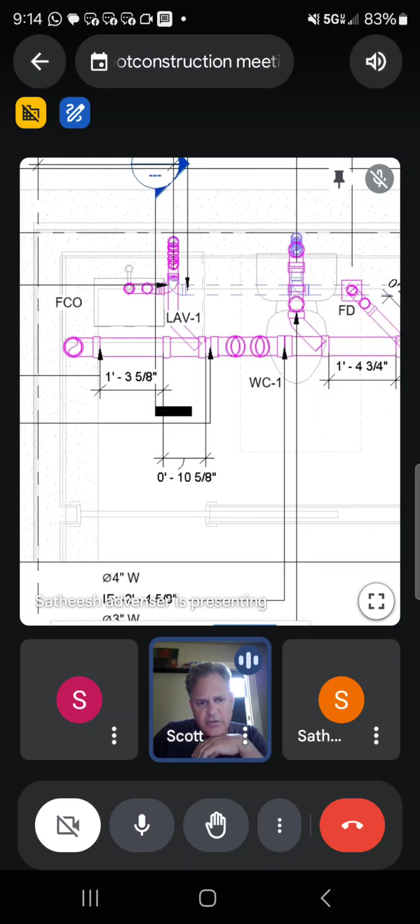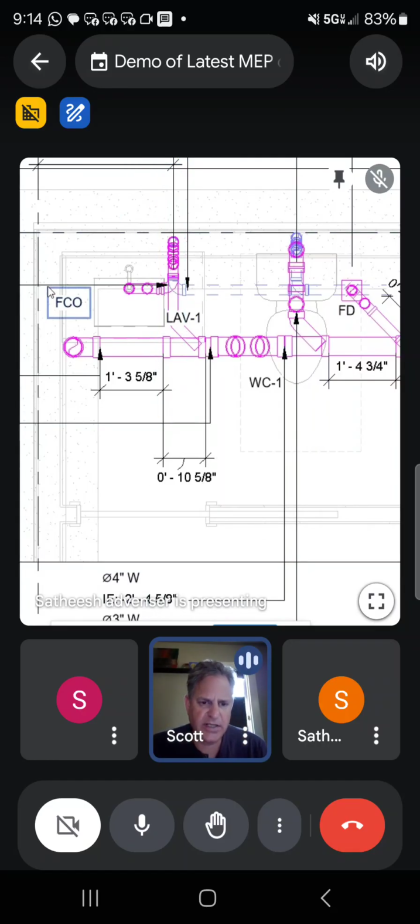Any penetrations that are coming through the floor, maybe pick a grid bubble. I see a grid bubble there. Maybe a grid line, and pull all your measurements left and right, in both directions, so a person can easily place. Am I making myself clear on where those penetrations are coming up through?